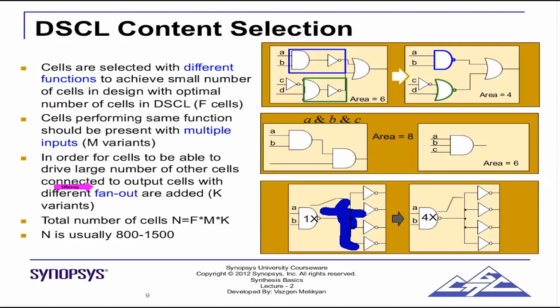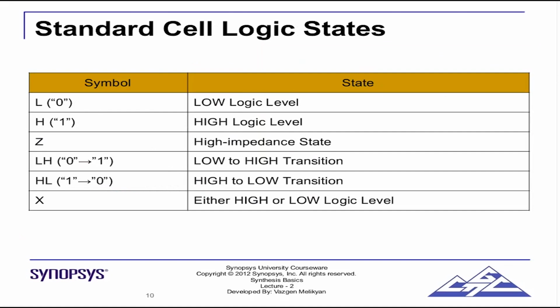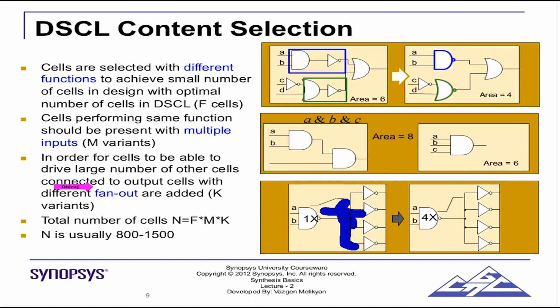A standard VT device means leakage current will be slightly higher than high VT, and there are low VT devices which have the highest leakage current, but again the low VT is the fastest. So the cell with a lower threshold voltage is faster but leakier. We discussed, right, that power and speed fight with each other. The faster the cell, the more leaky it is. So you should have cells with different functions, different numbers of inputs, different drive strengths, and nowadays also different VTs.